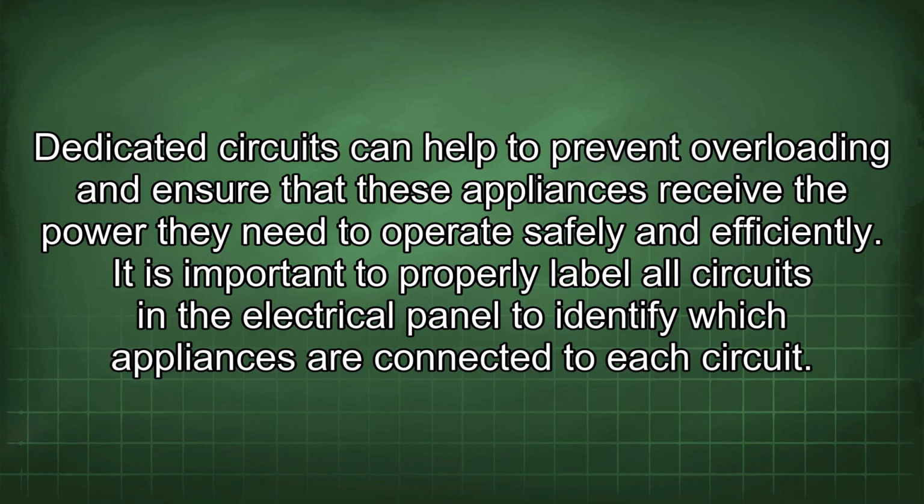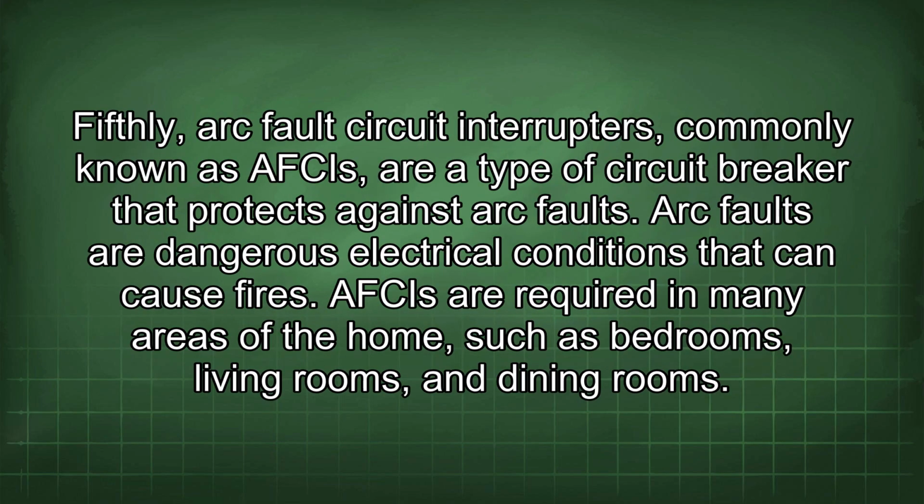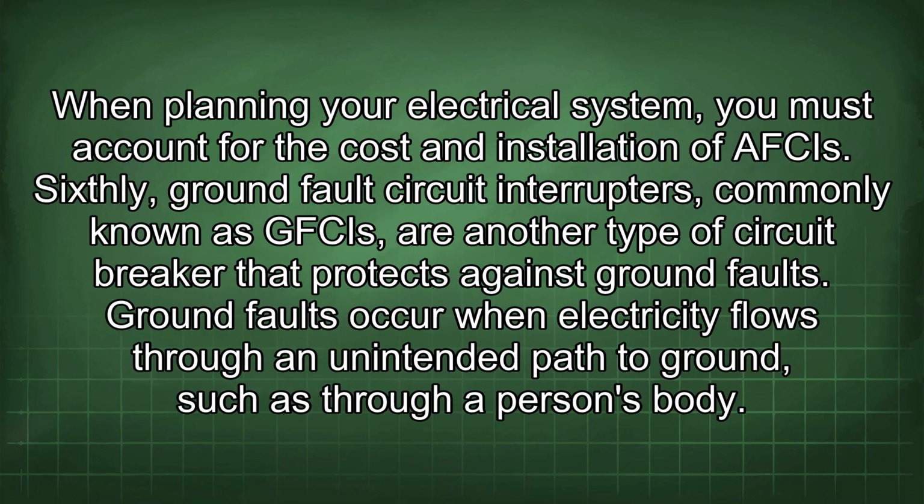to each circuit. Fifthly, arc fault circuit interrupters, commonly known as AFCIs, are a type of circuit breaker that protects against arc faults. Arc faults are dangerous electrical conditions that can cause fires. AFCIs are required in many areas of the home, such as bedrooms, living rooms, and dining rooms. When planning your electrical system, you must account for the cost and installation of AFCIs.